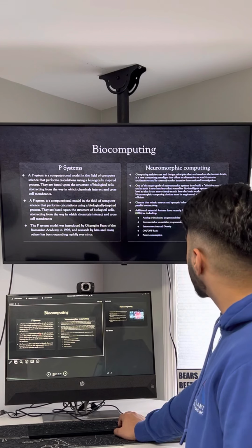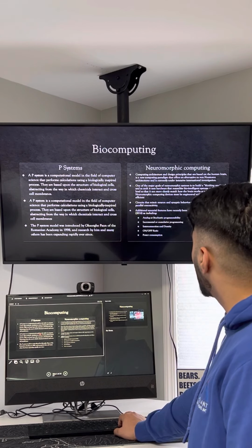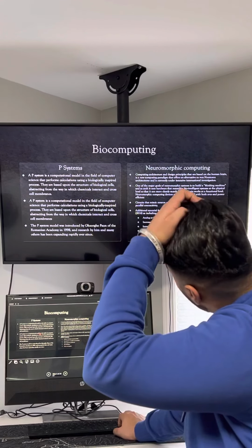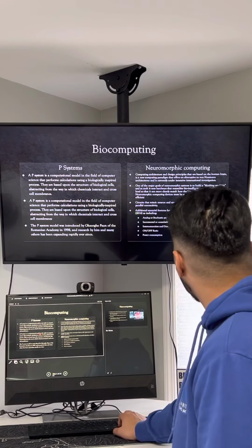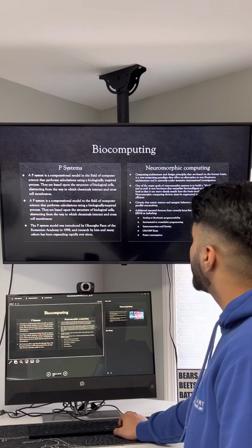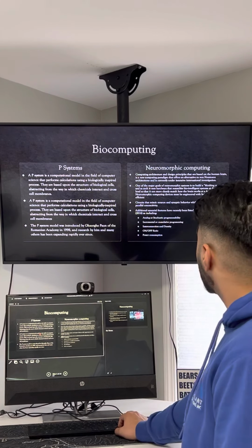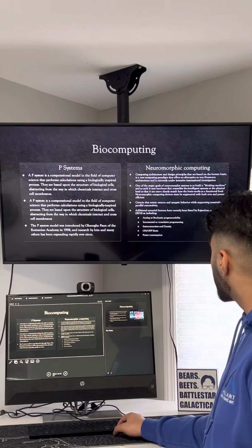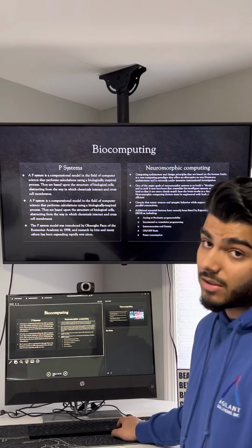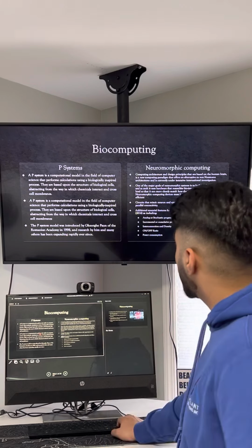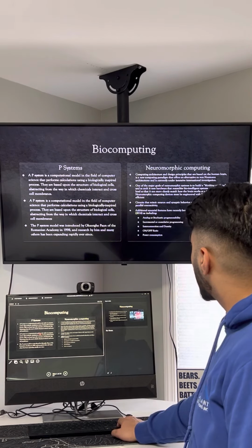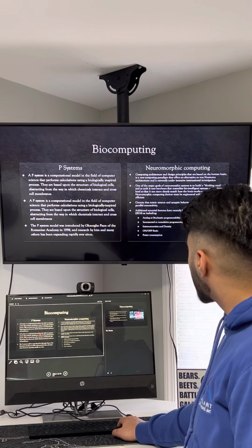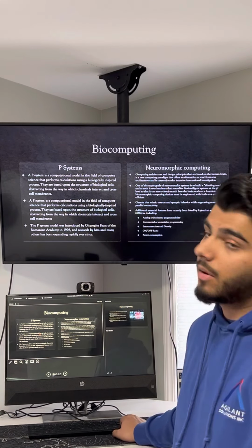Neuromorphic computing devices must be engineered to be both area and power efficient. Circuits that mimic neuron and synaptic behavior while supporting massively parallel connectivity. Additional essential features that have recently been listed by Rajendran and Alibart in 2016 are analog or stochastic programmability, interconnection and density, on and off ratio, and power consumption.